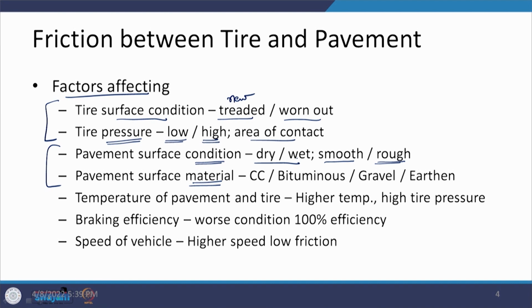So, whenever water comes at the surface it needs to be drained out, but in some cases it may happen that the flow is such that it remains wet, and if it remains wet and is also smooth, then probably this is going to create one of the worst conditions with respect to the reduction in friction. So, we have two sets here, one in terms of the moisture effect, another in terms of the rideability effect, and these two we can talk about separately as well as in combination with each other.